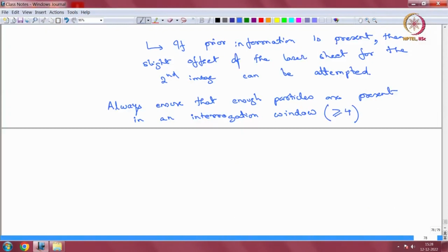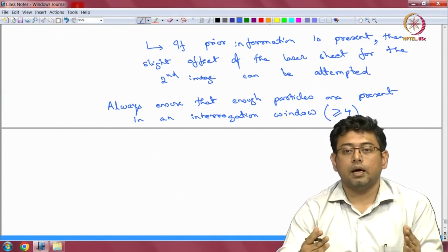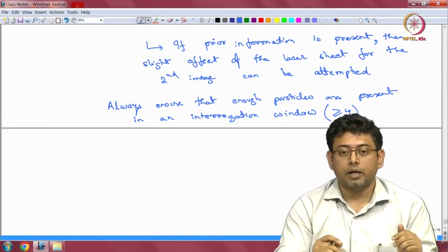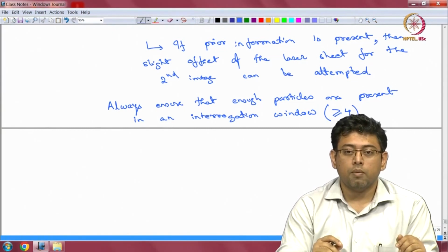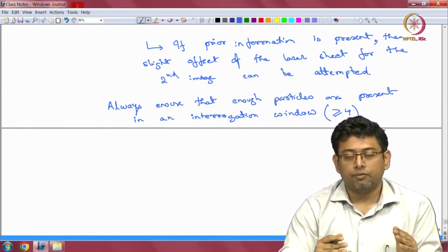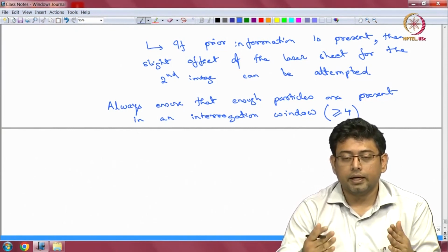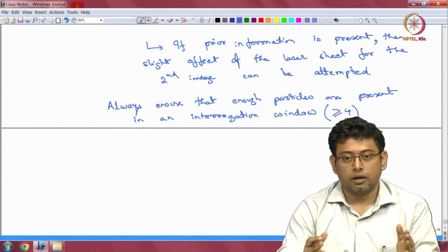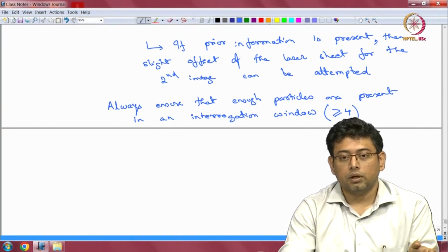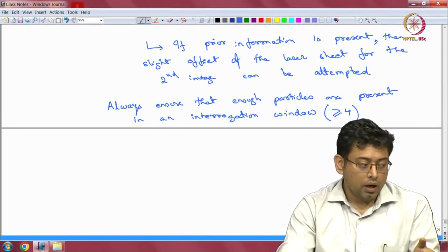For large-scale flows, stereoscopic PIV, where two different cameras are used with small angles subtended between them, is usually the most common. In that kind of case, you do require algorithms that will take in the data taken by the two cameras, synthesize it, and create three-dimensional data out of it.